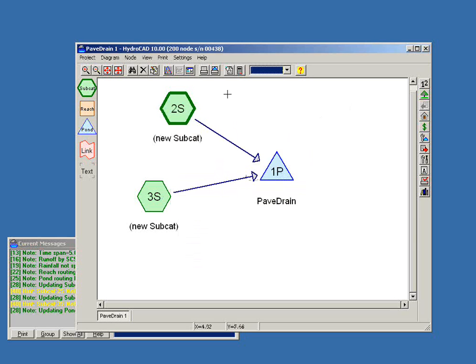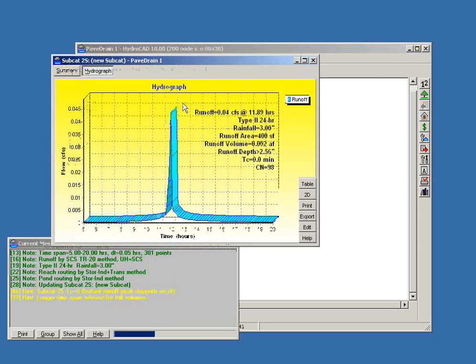So with that information, if we now double-click the subcatchment, we get a runoff hydrograph, or in this case, the rainfall falling directly on the surface of these blocks. With a very low flow rate, you notice just 0.045 CFS, and yes, we can adjust the decimal places or units there in order to give us more precision with these very small systems.